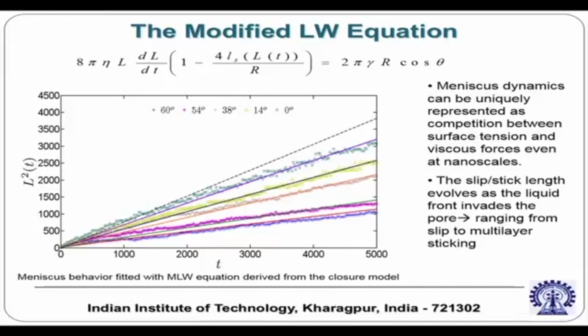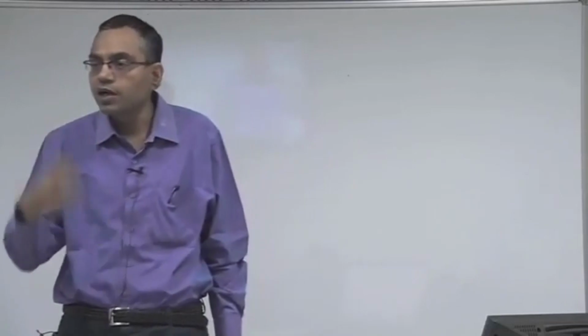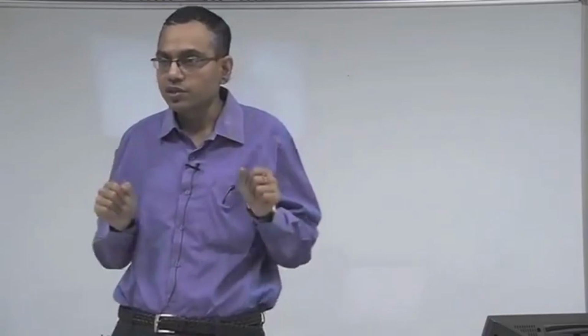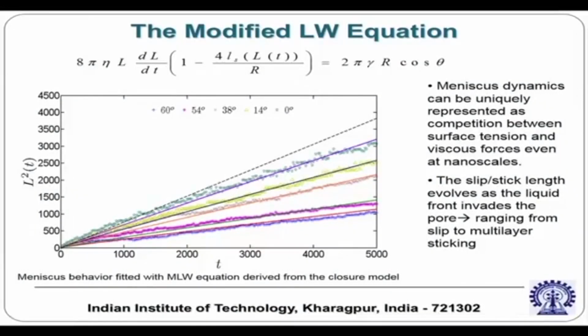Once you get the slip length versus non-dimensional acceleration data ready with you, it is like a database, then you do not have to do molecular dynamics simulations again and again. You can just use the Lucas-Washburn model in which you feed this data and you see that it remarkably agrees with the molecular dynamics simulation. So this is a kind of paradigm which we very commonly use for research in molecular simulations or research in nanofluidics. It is not just brute force molecular dynamics simulations, but some information from the molecular dynamics simulations to be plugged in with a continuum model.